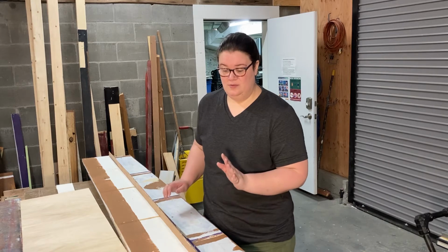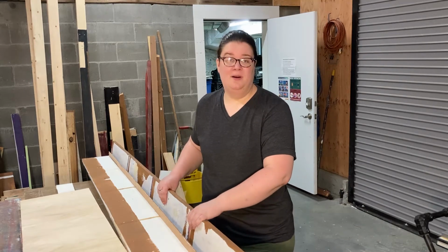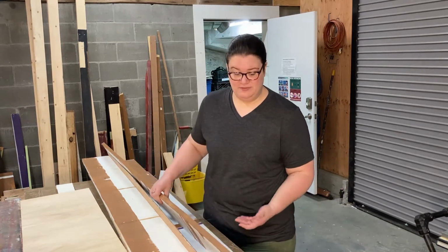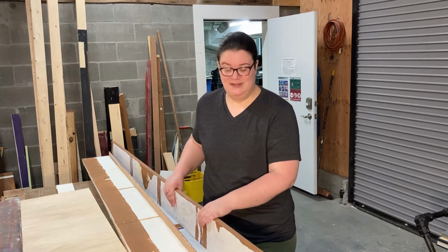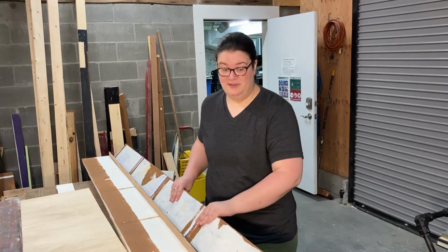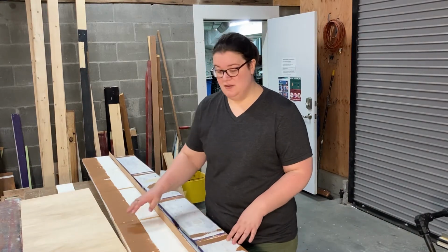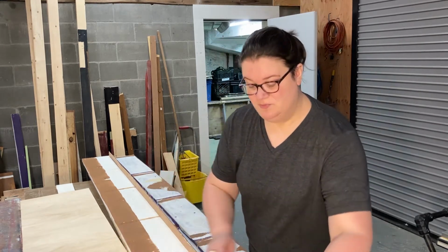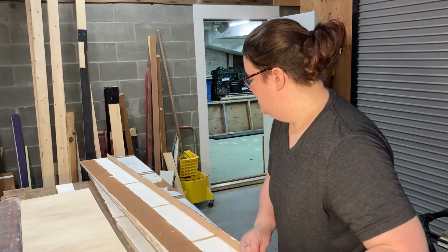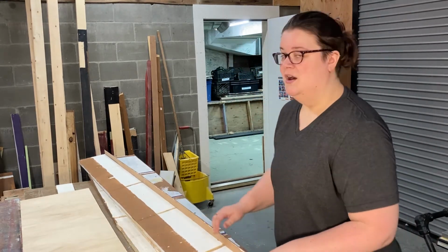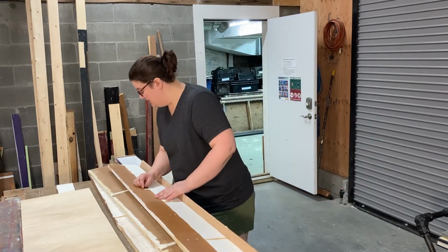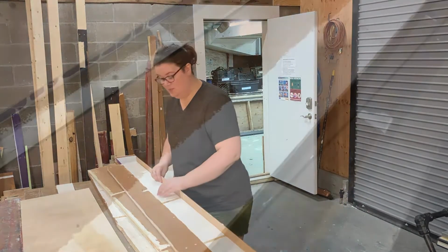So I am going to be using recycled lumber today. This is all 1x pine that has been ripped apart from something else that was constructed. Maybe it was a platform; it looks like maybe it had some shelving attached to it. It was scenery once upon a time, and now it's going to become a parallel for a platform. But when you're using used lumber, as happens pretty frequently in theater, especially when you don't have huge budgets, you're going to have to take a really careful look at what you've got so you're not running a bunch of metal fasteners through your saw. So here I can find, here's at least one nail sticking through this board I'll have to pull out.